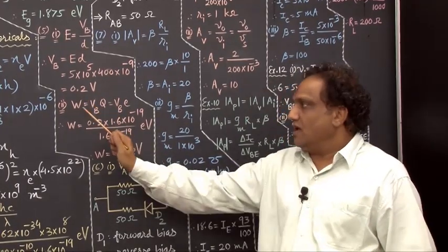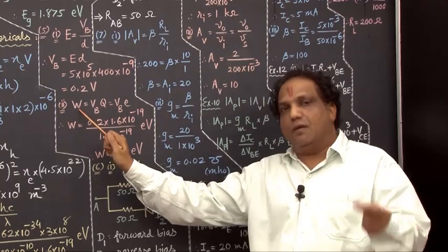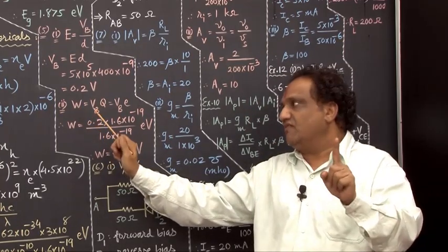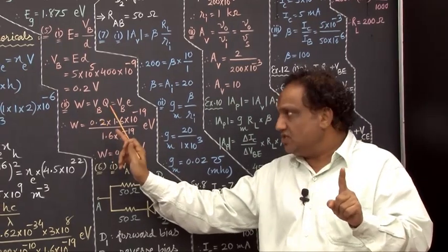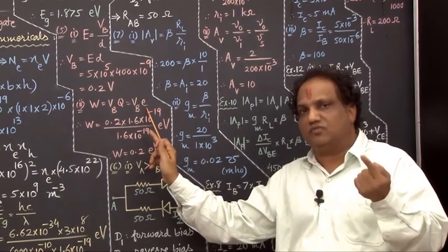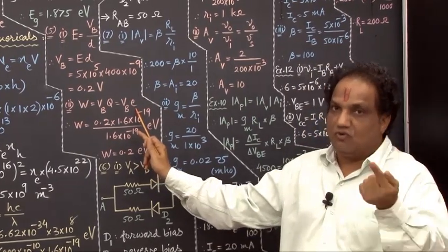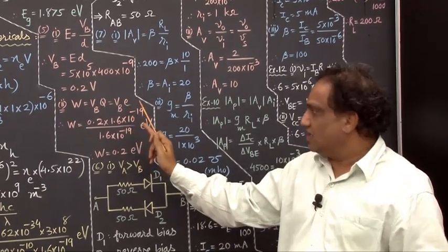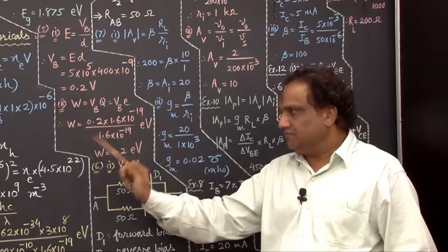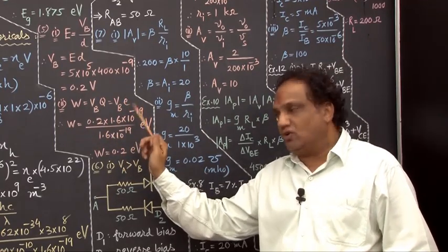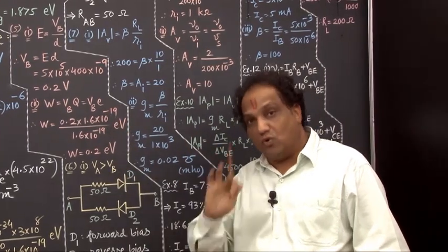Okay, come on. And what is the amount of work done? Amount of work done is given by the formula potential difference into charge. Potential difference is right now the barrier potential VB, and for charge I am putting small e because we are talking about one electron. What is the magnitude of charge of one electron? It is small e. This barrier potential we have found out is 0.2 volt, and the magnitude of charge of one electron is 1.6 into 10 minus 19 coulomb.